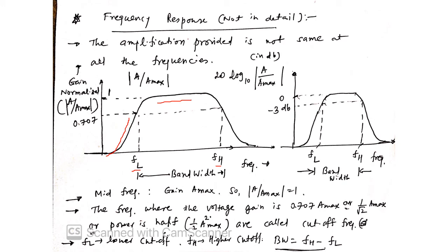So if I show here the curve graph of frequency versus the normalized gain. Normalized gain is A over A max. Okay, so at this point here it is maximum, which is 1. Okay, and on both of these sides the gain will be reducing, and after some frequency the gain is almost 0. That means the amplitude is going to be cut down. The waveform amplitude will be scaled at that frequency. It will be reduced at this frequency.